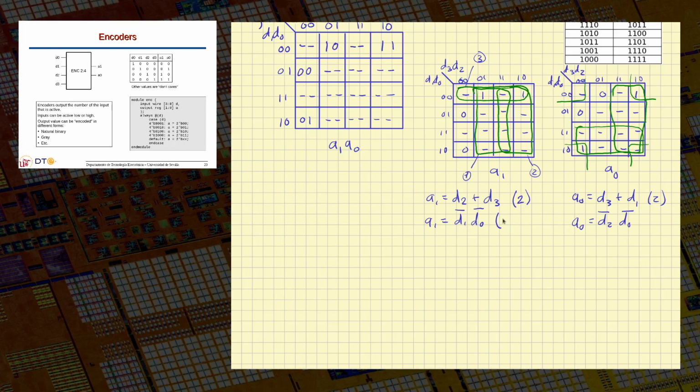But in any case, we have 2 plus 2 complements. So if we don't have variables in double rail, our cost will be 4, okay? We basically need an OR gate only, and an AND gate with complements here. Or I may try other options. Maybe we can do it like D2 plus D3.